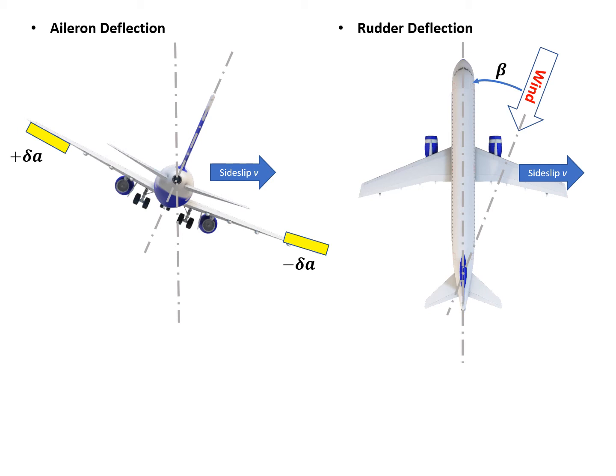Okay, so let's see the forces acting on the aircraft. We have lift, and the lift is tilted with an angle of phi. That's the bank angle, with respect to the vertical line. And also there is gravity, mg. Apparently this won't balance the aircraft. The aircraft is not in equilibrium. In order to maintain a steady side slip, there will be a side force from the fin, that's Y beta times beta, because of the side slip angle.